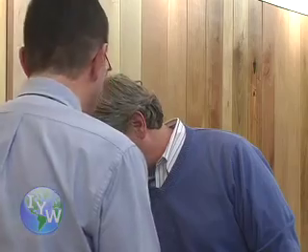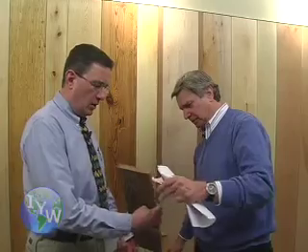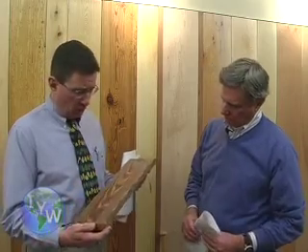Now, again, some of these others, what can you tell us about, for instance, this looks like a hardwood of some sort? No, actually, interestingly enough, it's a softwood. It's a southern pine, which has been pressure treated with a preservative. And of course, it's been in my office, so it hasn't been exposed to the elements. But the pressure treating of this would then allow it to be used on a deck behind your home or at a dock or somewhere. And you know, it's going to last for many decades without being attacked by fungi, insects, or if it was in the water, marine organisms. Right.